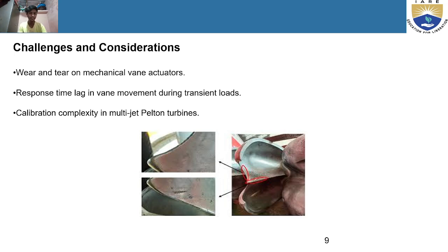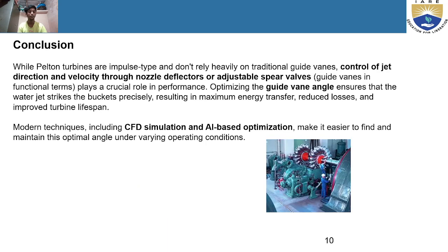Challenges and considerations. The main challenges are wear and tear of mechanical vane actuators, response time lag in vane movement during transition load, and calibration complexity in multi-jet Pelton turbines.